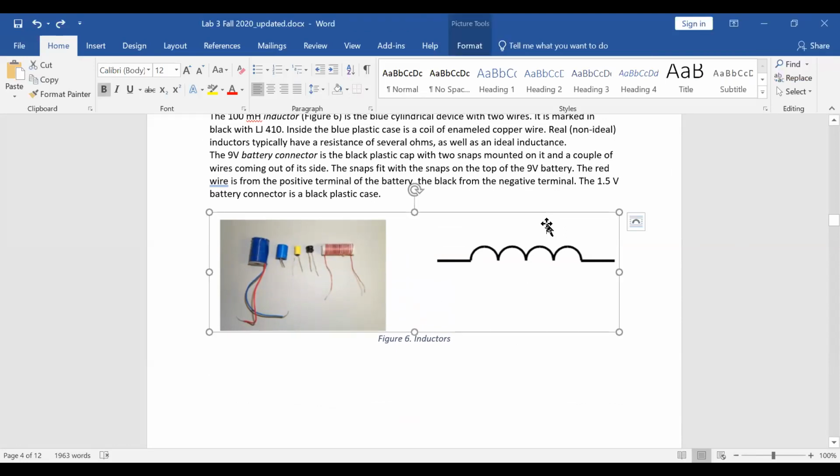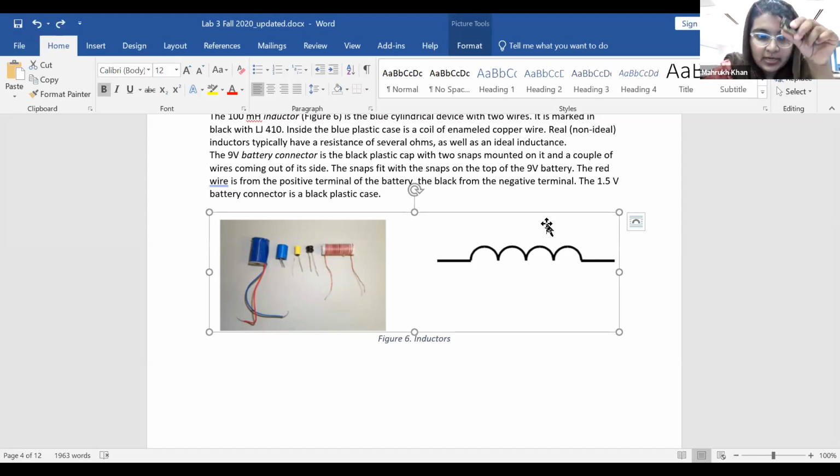Yep. Okay. So then there is this holder. I just want to tell you a very important thing about this holder. This particular holder is actually connected in series, which means that you cannot get 1.5 volts out of it. You can only get 3 volts out of it because both are connected in series. They will not work if you just want to get 1.5 volts. If you want 1.5 volts, there are separate holders that you can get and use.